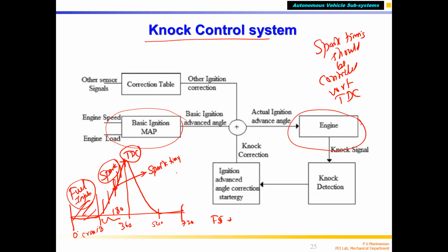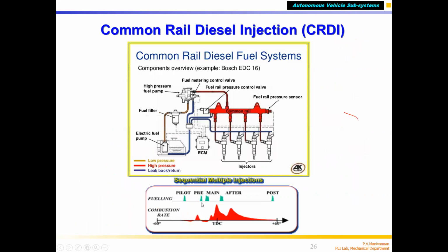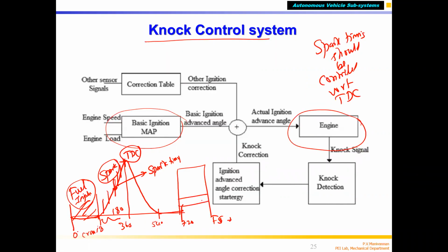Suppose, what happens during this time? Say compression starts when the piston is at BDC position, correct? So the compression stroke is moving up. Here you have your spark plug, correct? This is your exhaust, this is your inlet, and both are closed. Compression will happen and the piston is moving up from BDC. Up to where will it go? It will go to TDC, correct? So already I told you this is the TDC condition, and this is your BDC.